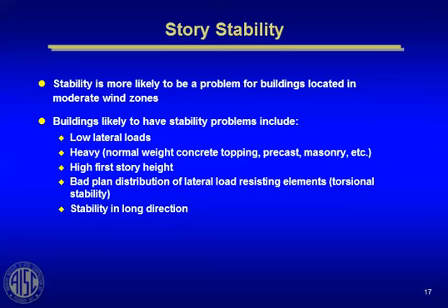And this first came to my attention when we were designing a building down in Mexico, in the central part of Mexico toward the West Coast. They had no seismic to speak of, and very low wind loads and very heavy building materials that they use down there. And we found out that on that kind of a building with no lateral loads, that means it doesn't have much lateral stiffness because you're not putting much lateral load on the building.